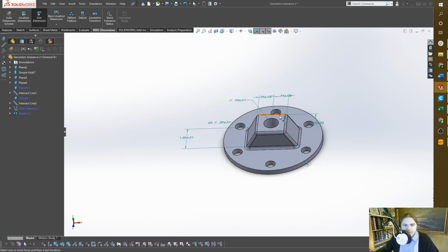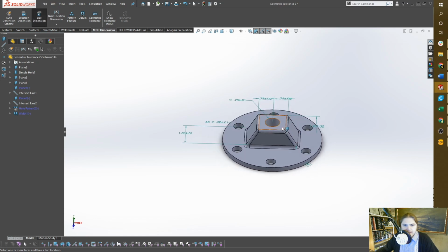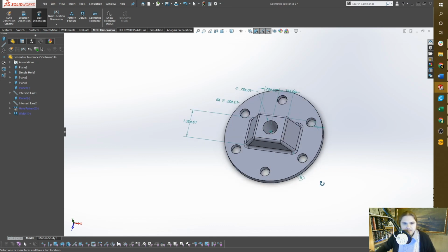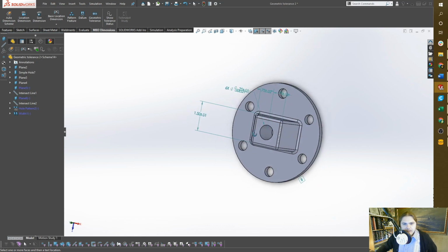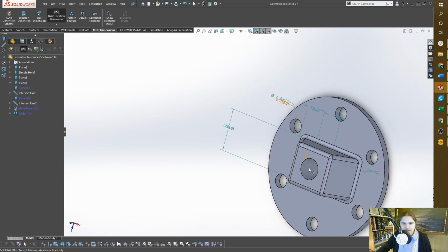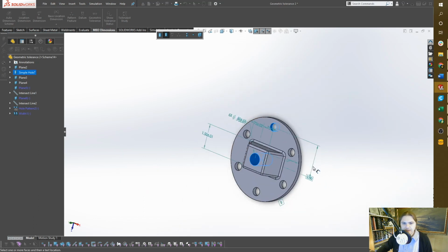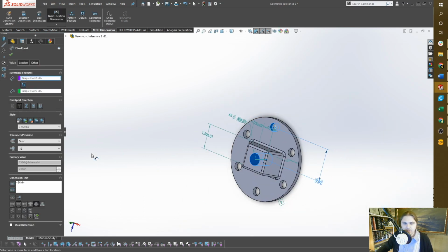We're going to need an angle. The way I had this set up, this is determined by an angle, so we'll have to use an angularity tolerance on there. And then, as I said, I can't find a good option to dimension the position of these holes with a basic dimension, so for our use right now, I'm just going to use a linear one from the datum B up to that one, and we'll call that good.